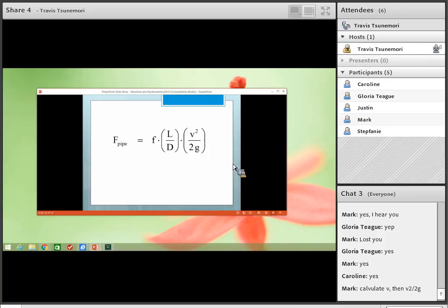Okay, I'm just getting my notes here. So V of the pipe is going to be Q divided by the area of the pipe. And our inner diameter is 0.5 meters. So if we run those calculations, we get that our velocity is 20.4 meters per second. Okay, and then the next thing we're going to do is calculate our Reynolds number. We can calculate V squared over 2G. I didn't happen to do it yet. So our Reynolds number is going to be dV rho over mu.